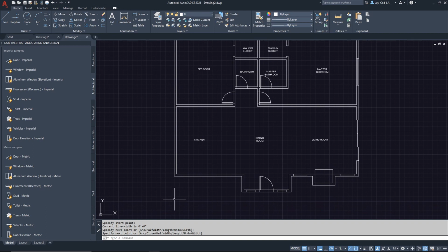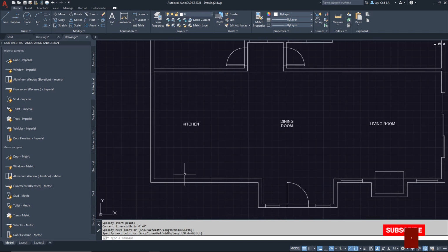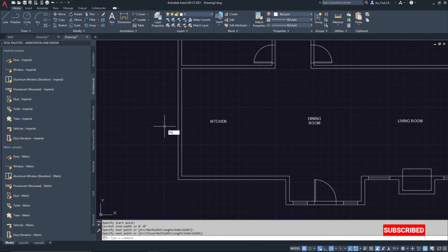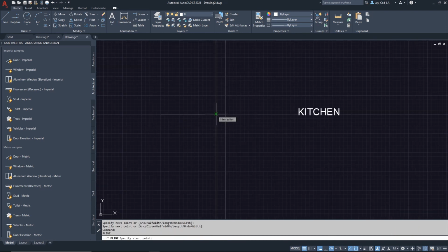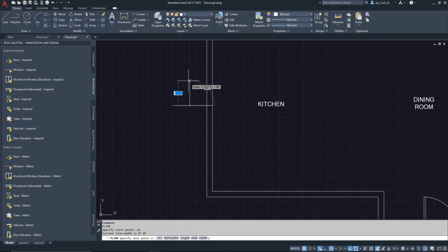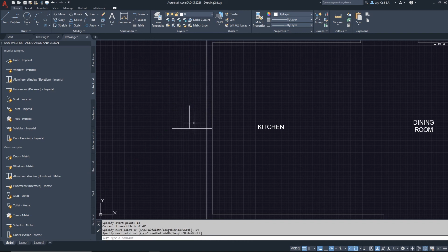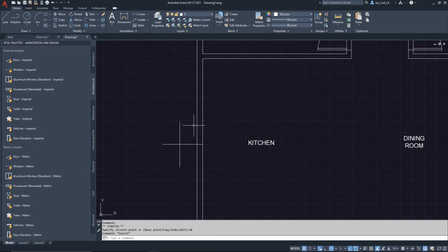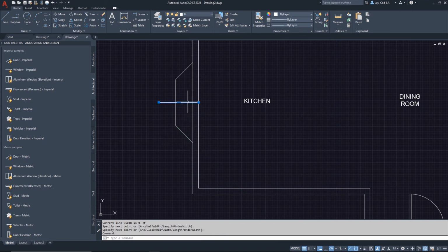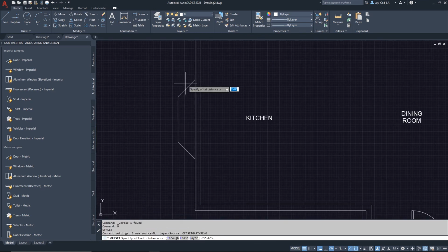For the kitchen, let's probably do a really wide window over here. Let's say we want to create a bay window, so I'm gonna reference this middle point up here, up to here, and then I'm gonna reference it up by, for example, 18 inches like this, and I'll go 2 feet up, then I'll select it and slide it down, and the total should be like 48, and then from here I'll do 45 degree lines. Okay, and I'll get rid of this, and then I'll offset by 6 inches since this is an exterior wall.